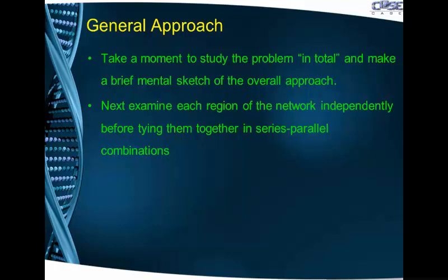Then examine each region of the network independently before tying them together in series parallel combinations. That is, you break the complex circuit into segments and see which components are in series, which components are in parallel, and what is their combination.